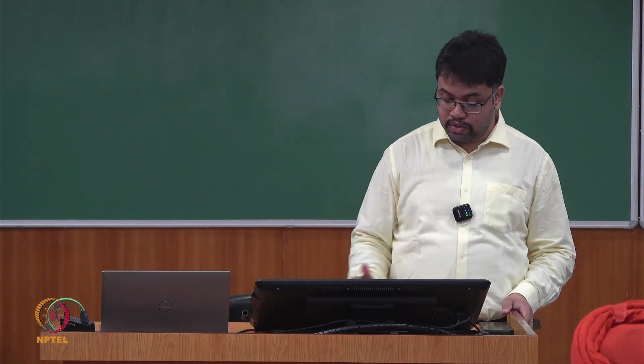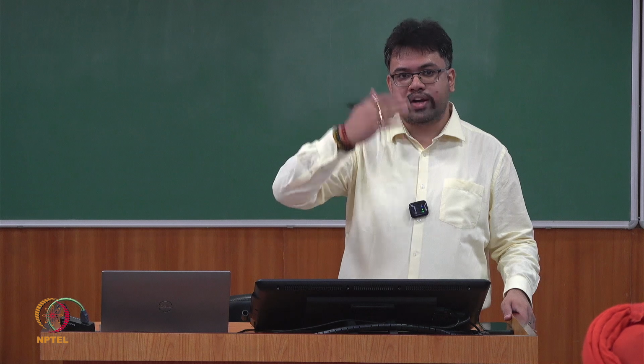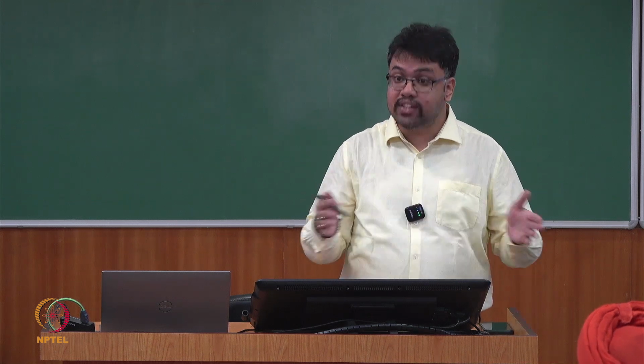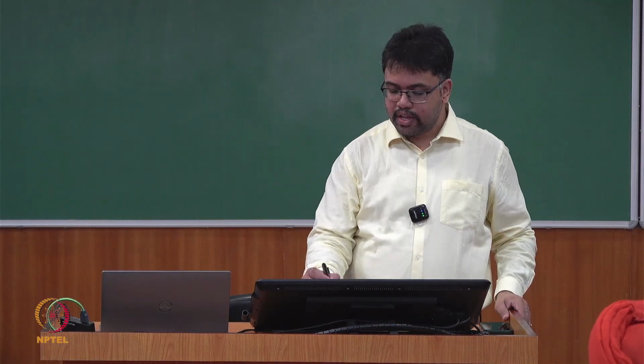So there, our main equation was, once we get that lambda value, we substituted it, so four solutions of lambda come for the beam. And once we do it for a bar, maybe there will be two solutions. So that depends on the order in the spatial domain. Based on that, how many coefficients will come, we will decide.